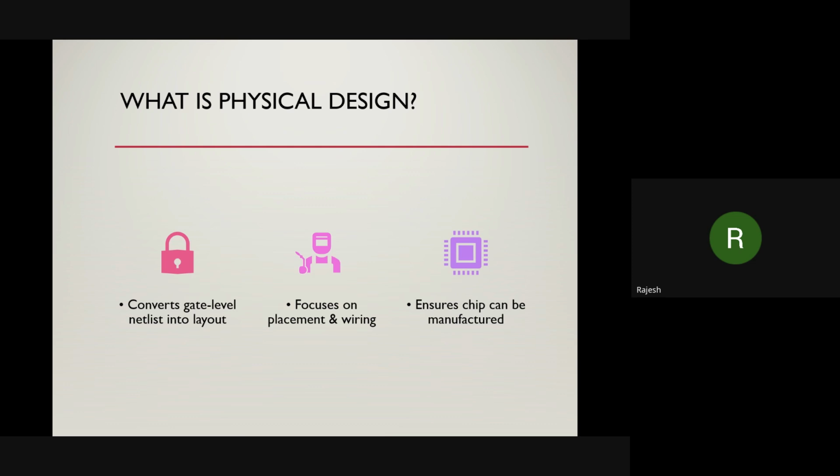With all this circuit, what you need to do is place this circuit and create one layout. Layout is nothing but the chip you need to create with that, and you need to place that circuit inside whatever area they have given. We call physical design the PNR stage, that means place and route. Place and route is nothing but placing all the standard cells, the elements in the circuit, inside the chip, and routing means wiring, connecting them with the proper width and length.